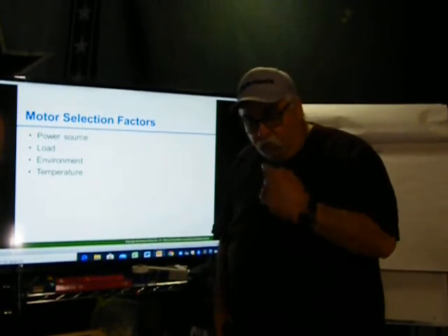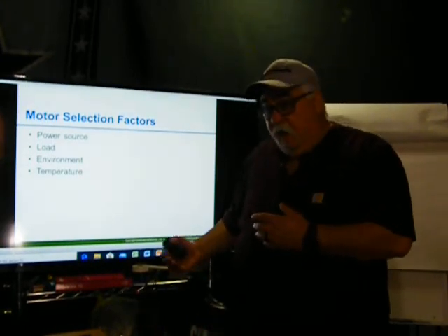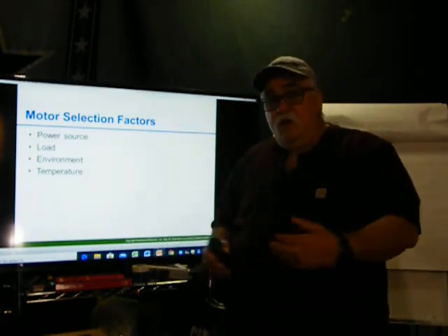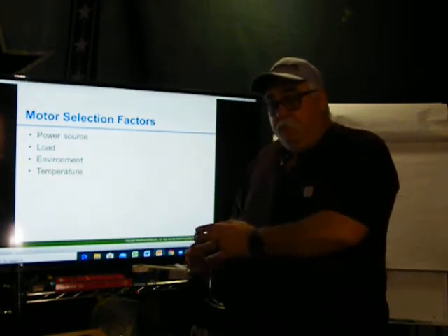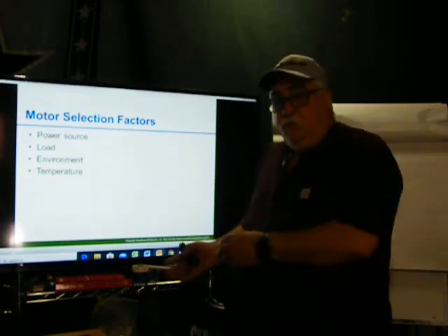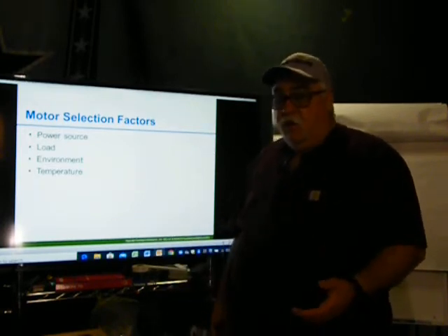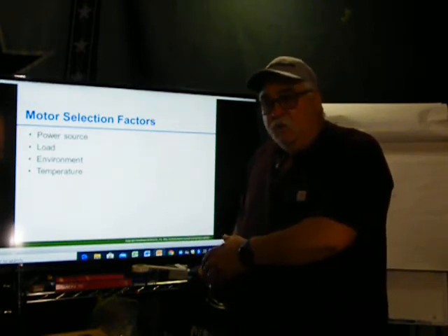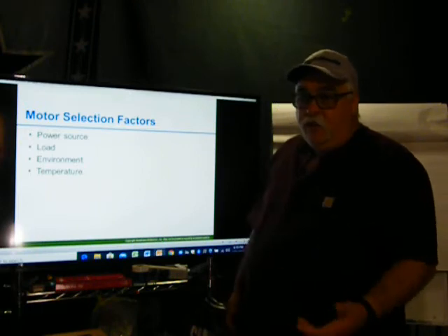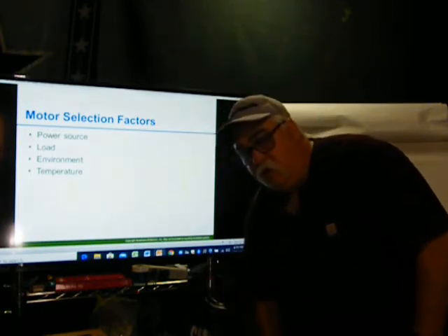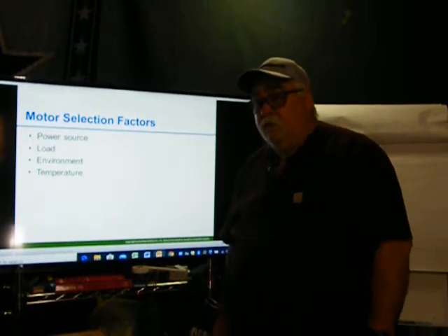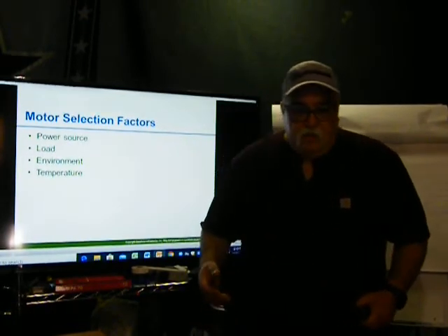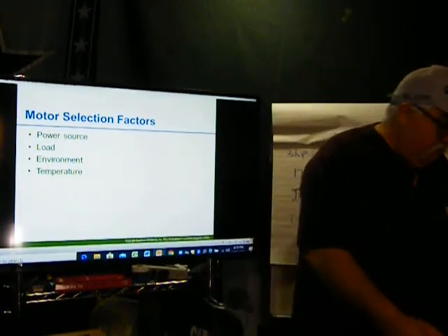We used to have guys, when a motor went bad, go out and change the motor. They'd look at what they had in stock, and a 10 horsepower motor blew up, but they had the same frame number for a 15 horsepower. So they put the 15 horsepower in, and all of a sudden the motor wouldn't work. Why? Everything on it, the protection, the wire, and everything else, was sized for a 10 horsepower motor. So they were having problems. We had to go back and redo everything, and then they started noticing that their efficiency wasn't the same. Now they had a bigger motor, but they didn't need it. Okay. The environment, that's very easy to say.